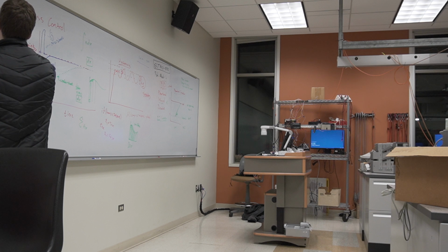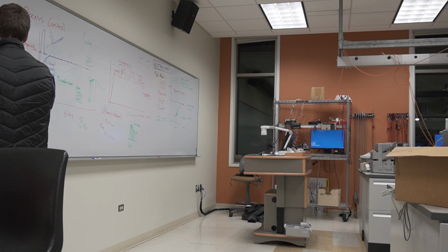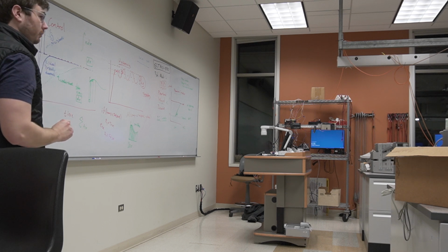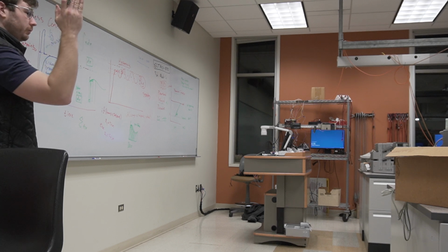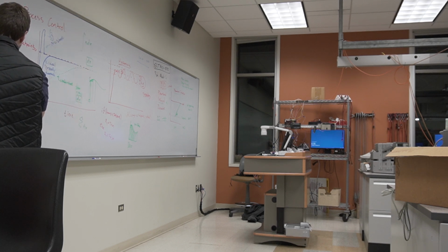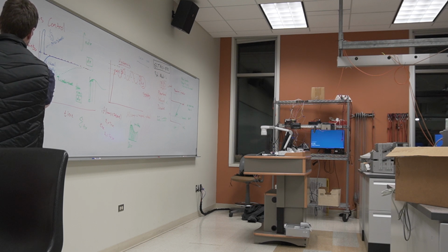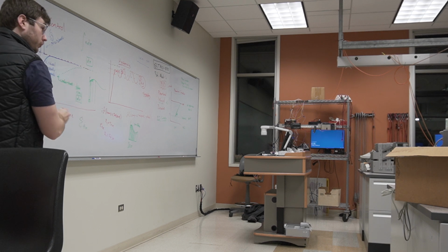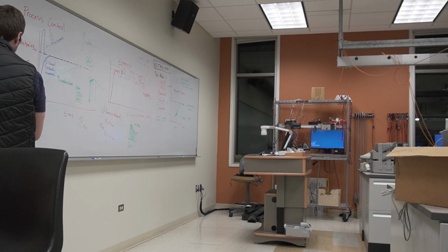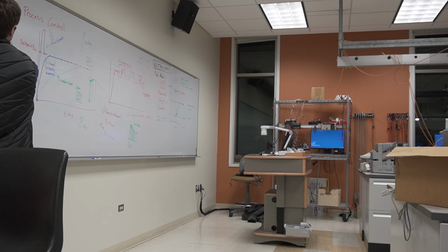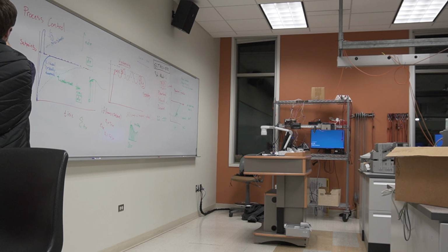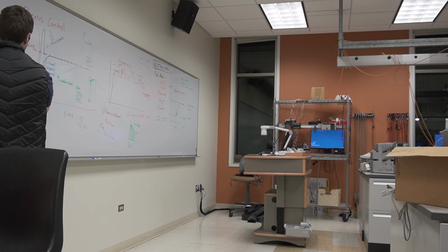So when we go to do a motor movement, we have the motor movement given to us by our P controller, the amount we need to move as demanded by our P component. Most of the movement is done by the proportional controller, and now we need to add a little bit of movement from our I term, which is growing and growing. Soon enough, this I term will be sufficiently large to trigger a motor movement. It'll go click, or it'll slowly creep up. The motor will start getting more and more power fed to it as this number goes up, such that it creeps smaller and smaller.